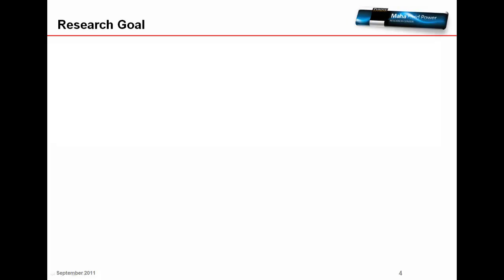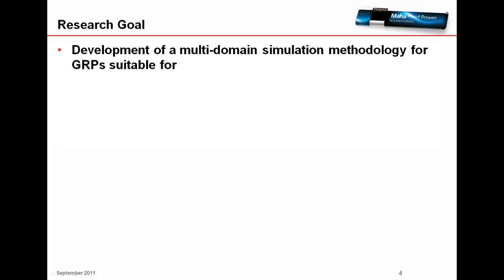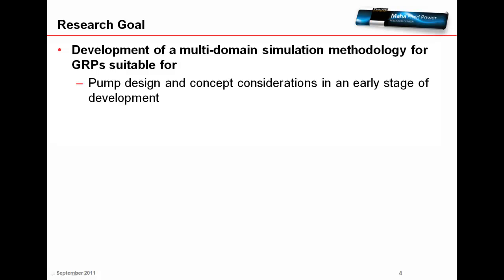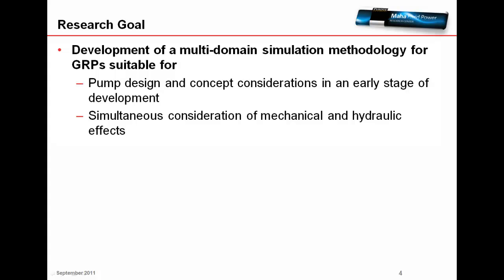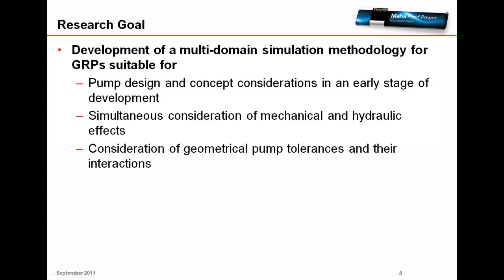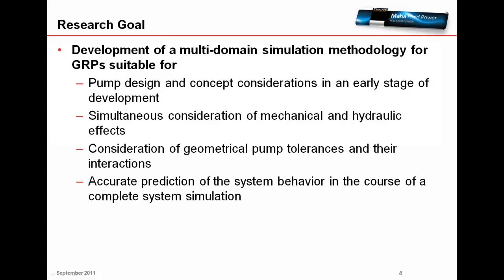The motivation of our work and the research goal can be summarized as follows. To develop a computational multi-domain simulation methodology for gearing pumps which is suitable for the pump design and for concept considerations in an early stage of development without having detailed CAD data available. The model should consider the mechanical and hydraulic effects as well as the pump tolerances and their interactions, and in that way an accurate prediction of the system behavior in the course of a complete system simulation should be enabled.